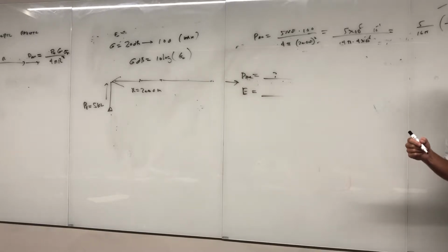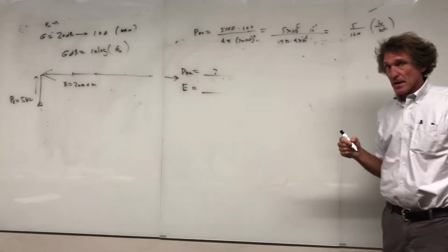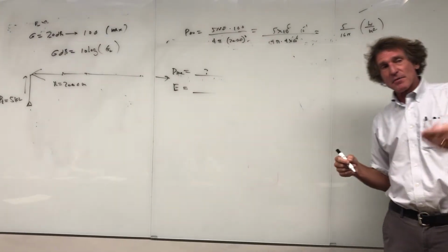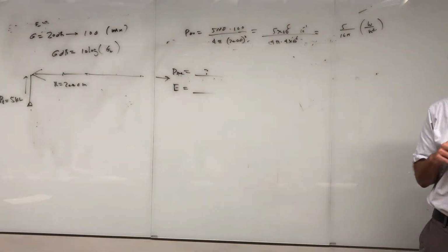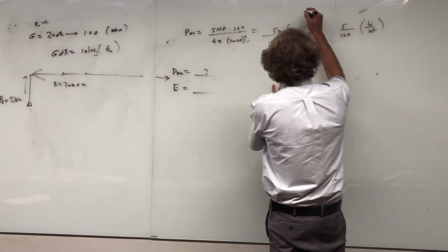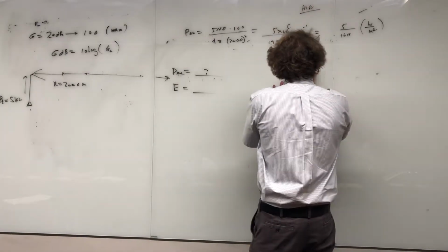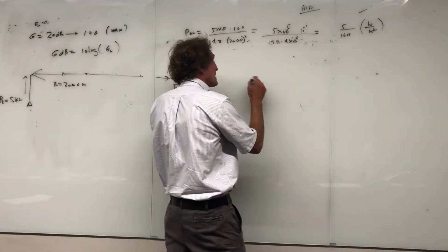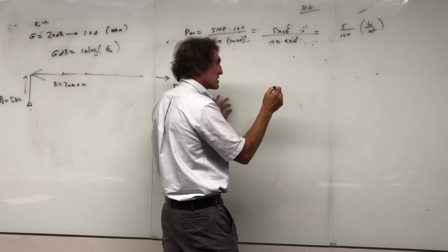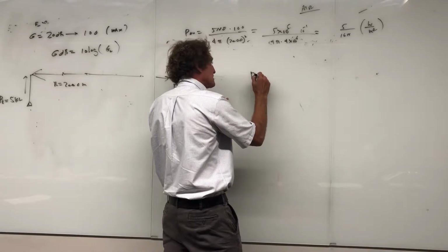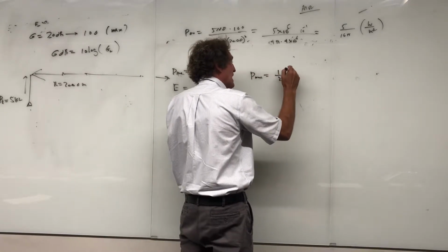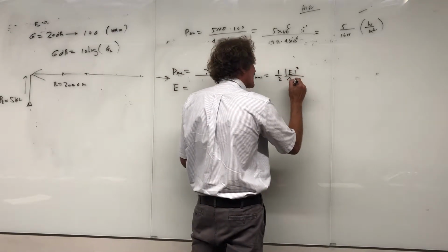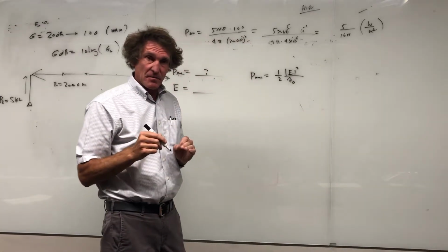Now remember, that's power density. It's max power density, right? That's at that range. So what's the electric field? Do you remember from propagating waves how to get the electric field from the power density? If you're in, let's assume this is air too. This is air. Anyone? Good. V squared over R. Yeah, you know that if it's lossless, if it's air especially, we know that the average power density is equal to 1/2 the magnitude of the E field squared, divided by eta naught. It's not the RMS value, it's the peak value, pardon me.